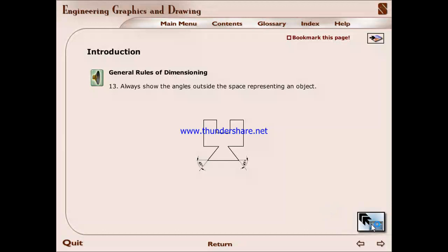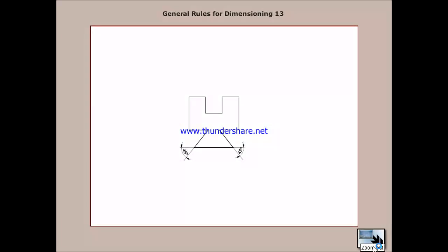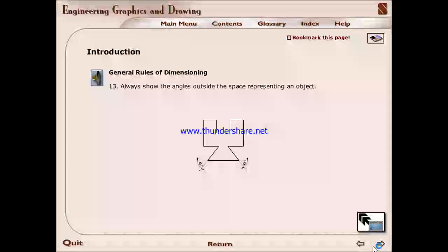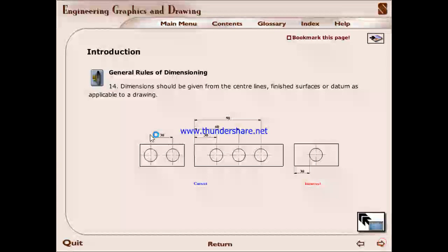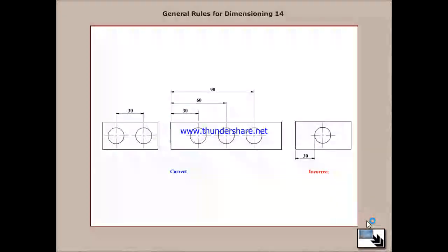Always show the angles outside the space representing an object. Dimensions should be given from the center line, finished surfaces or datum as applicable to a drawing.